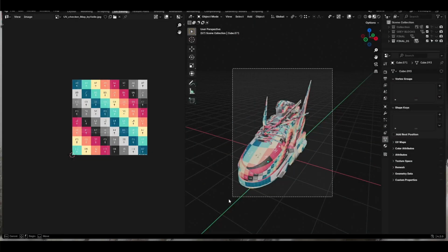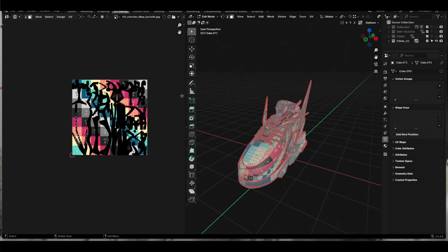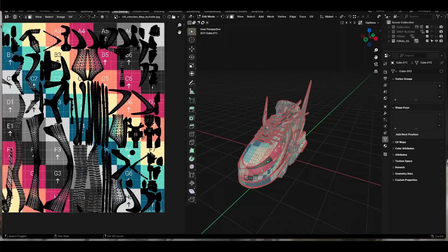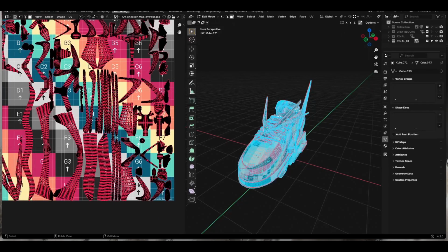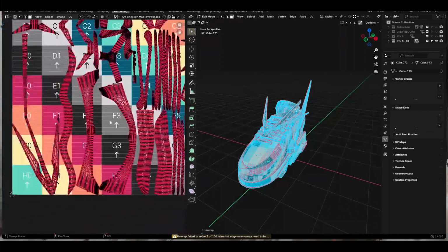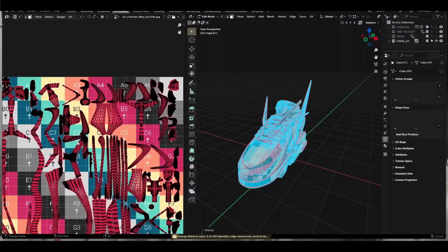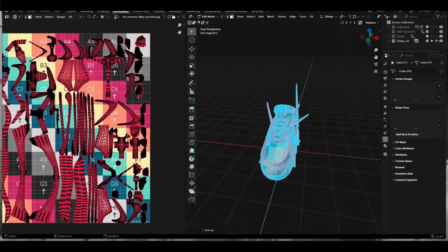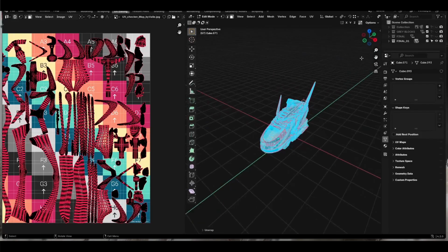Every time we select everything here, then tab, you can see the UV here. When we try to unwrap them, let's say I'm gonna unwrap them once again. U and unwrap. You can see the results here. The UV is distorted and they're not in the correct scale. The reason here is that we forgot to apply the scale and transform for our model.